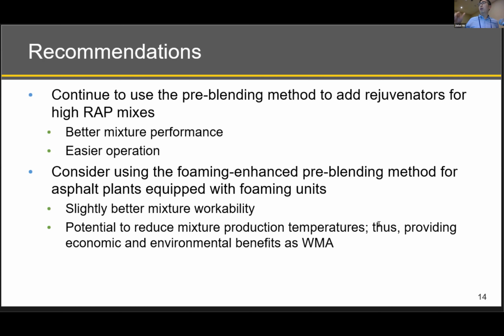First of all, it provides better workability and has a potential to improve compaction in the field, which is always a plus. And also it allows us to look into the possibility of reduced production temperatures. As the asphalt industry moves toward net zero, trying to reduce carbon emissions, this is one of the effective approaches to achieve that. So that's why we provide that recommendation, to kill 2 birds with 1 stone.